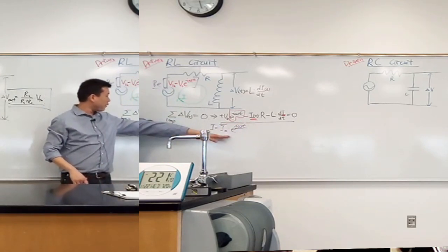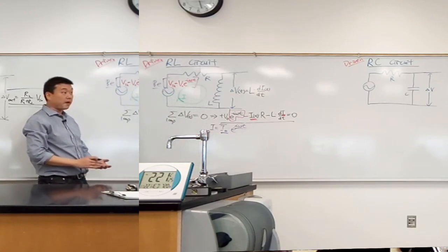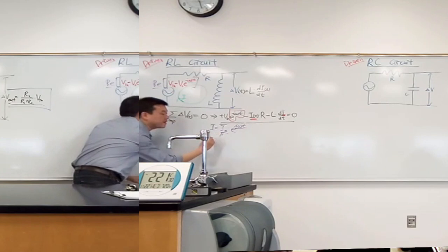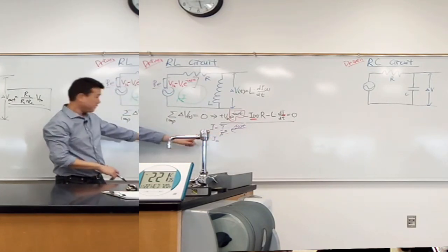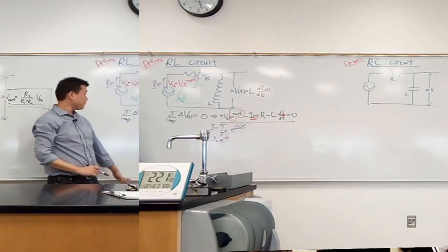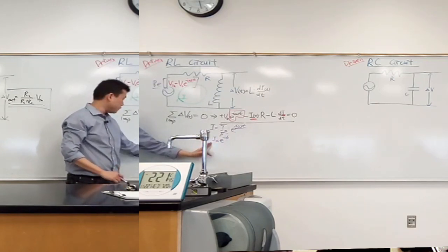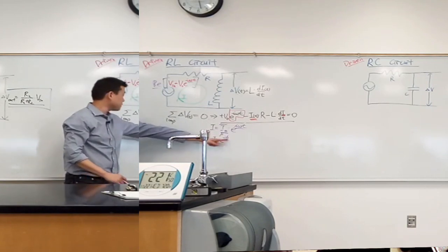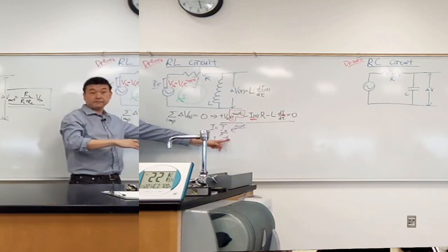Let me rewrite this one more way. In fact, I can rewrite this constant complex coefficient in a way that it separates our two aspects well. I can rewrite this as the real value I naught times a phase factor, e to the I phi. So this is a two parameter complex number, but each of the parameters has a very clear meaning. This is the maximum value of current. This is, on which cycle are you starting? Is the current varying as cosine or sine?